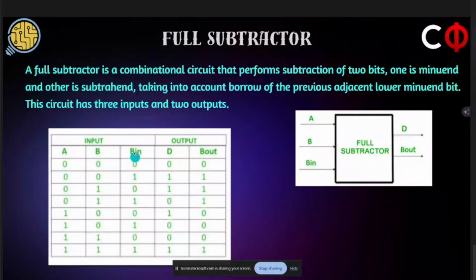So you have 0 minus 1, you will have difference 1, borrow 1, and then you subtract and you have another 1 in B in. So your difference will be 0, B out. You can just go through the truth table. It's quite easy.